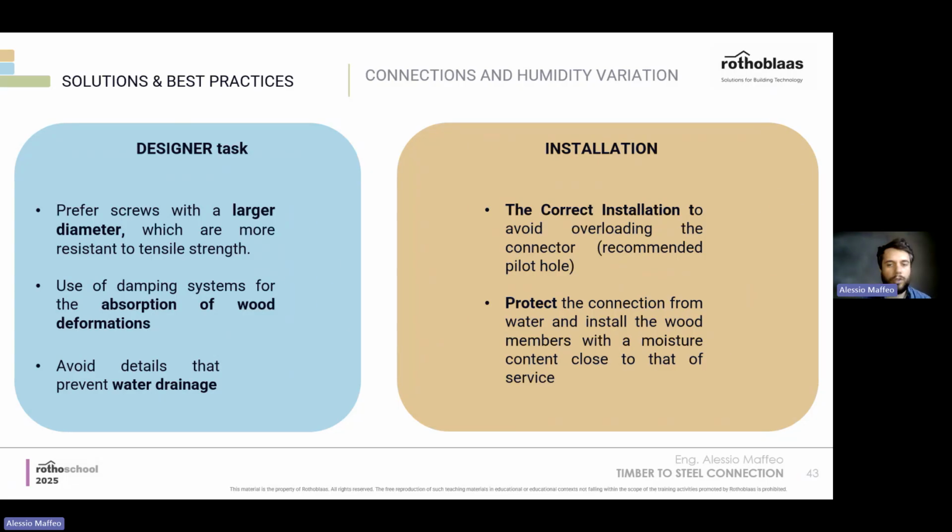But if we have a shorter screw, it means that we are not taking as much swelling into the fasteners, because shorter screws will mean a lower depth in timber, so the swelling is not as impactful on the fasteners. So we want to prefer larger diameter fasteners and maybe shorter, instead of a lower number of fasteners but longer.